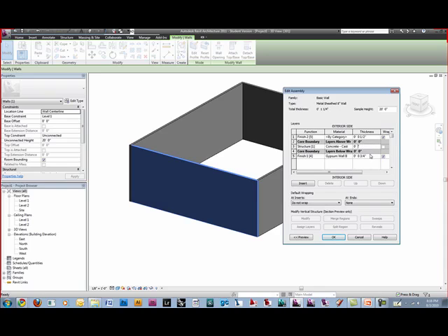It doesn't really matter. And then the structure, we're basically creating the rest of it, so you don't have to. We could just say 6 inches. We specified that it was 8 inches, and it tells you your total thickness is 7.5 right now. So I could go in and say this is 6 3/4 just to make it 8 inch. That way we're matching whatever we've called it.